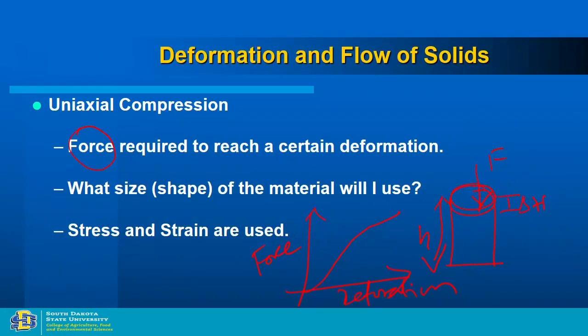So we will be using different dimensions and they will be using different dimensions. In that case, we just need to account for our dimensions in our test so that the final result can be compared between two labs. And that's what Ashish is thinking, that we have to convert this data. Instead of using force as it is, we have to convert force into stress and deformation into strain.